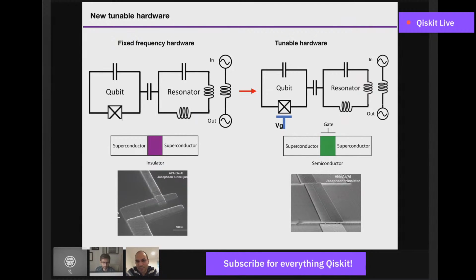You all find answers to all of these questions one way or the other. But at face value, a SQUID seems to me slower and also consumes a lot of power when you scale up, and it will be a problem. With the gate, you don't have those two problems. In a SQUID control, you have flux noise. Here you have charge noise through the gate. Which one will turn out to be worse or better? I think we really need to look at it.